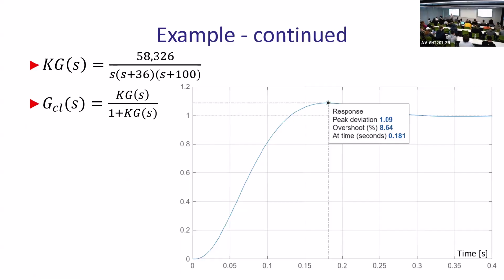All right, so it's a much better response, but with higher overshoot. You will have to revisit if this is okay. All right, any other questions on that exercise? Weren't we designing for a percent overshoot of 9.5%? We were designing for 9.5, yes, and we've got 8.6, which is better in a sense. 9.5 or less. Again, it's not an exact thing, so you will never get exact because it's not a second order function, and you have all kinds of approximations here too. So this is close enough, yes.